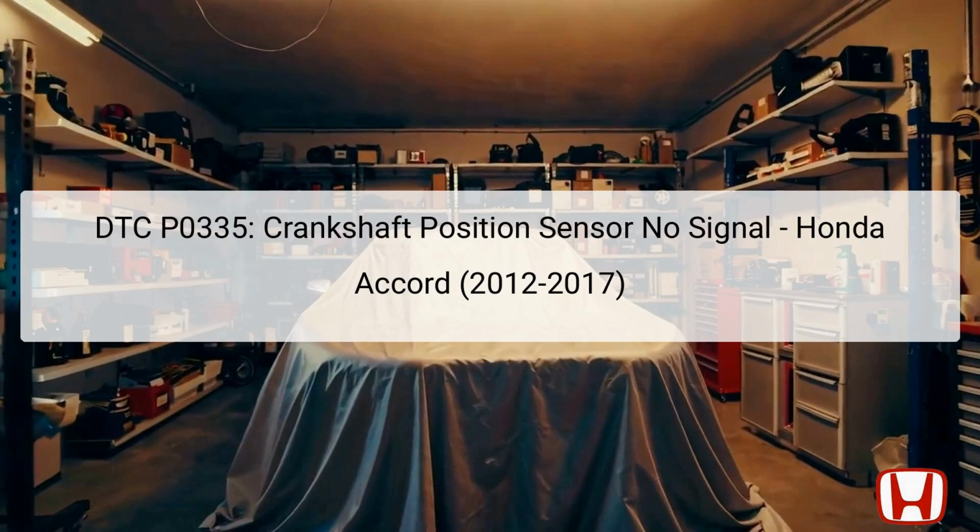This presentation focuses on the diagnostic trouble code DTC P0335, which indicates a no-signal condition from the crankshaft position CKP sensor in the Honda Accord models from 2012 to 2017. The CKP sensor plays a crucial role in the vehicle's engine management system by detecting the injection and ignition timing for each cylinder, as well as the engine speed.